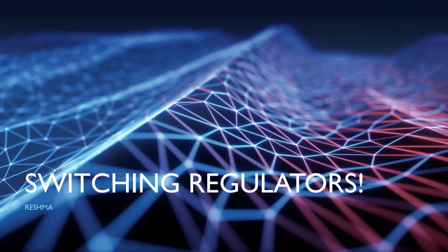In our previous videos, we saw how we can use transistors, Zener diodes, and op-amps together to get a regulated output. We noticed that maximum loss is present at maximum load and maximum input. Hence, if we use a switching element, we can reduce this loss. I am Reshma, and today we will talk about the need for switching regulators.